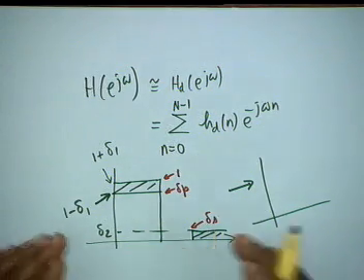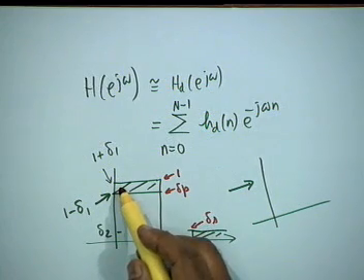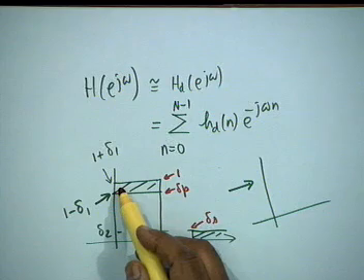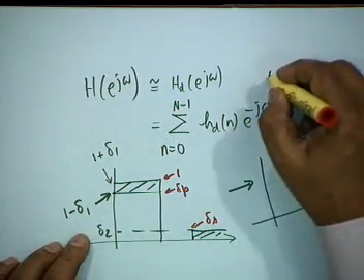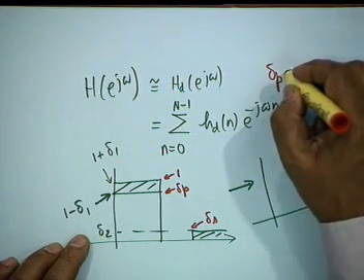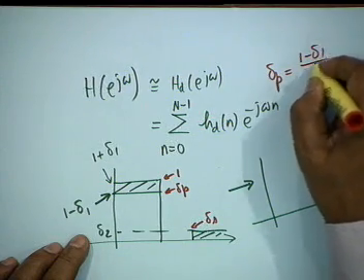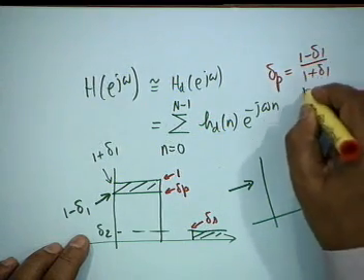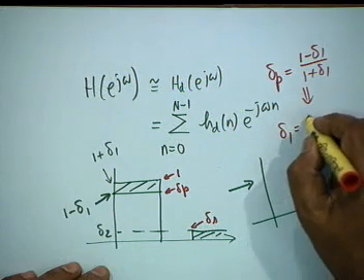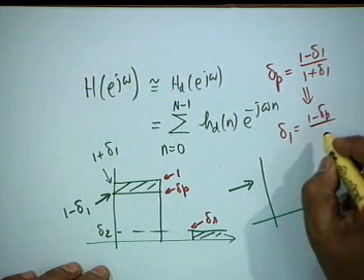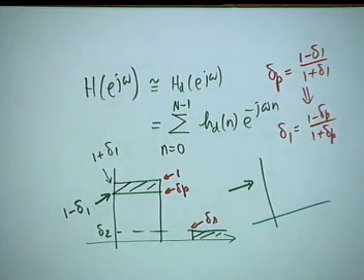Converting from one spec to another is not a problem. All you have to do is normalize by dividing by 1 plus delta 1, and therefore your delta P would be equal to 1 minus delta 1 divided by 1 plus delta 1, which gives you delta 1 in terms of delta P as 1 minus delta P divided by 1 plus delta P. Is that correct?